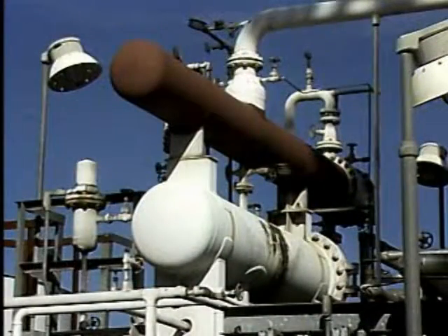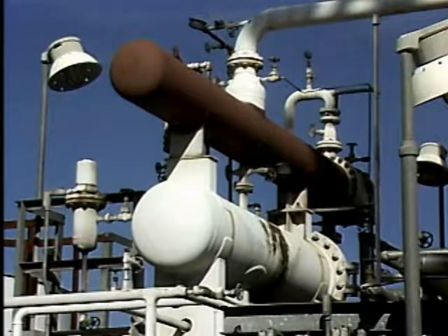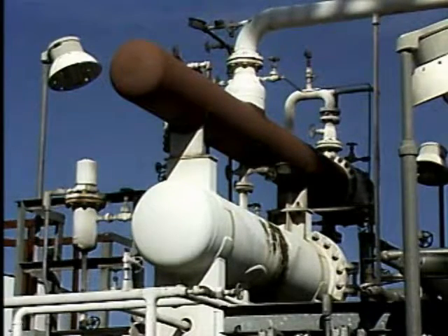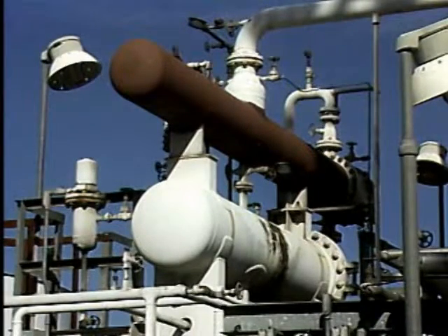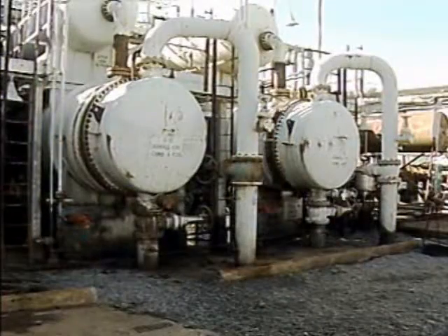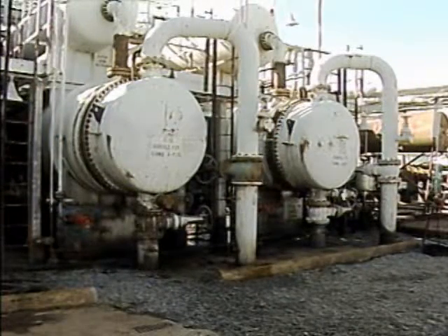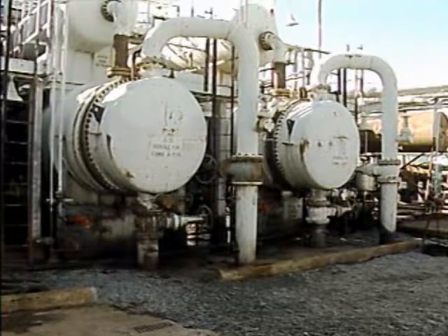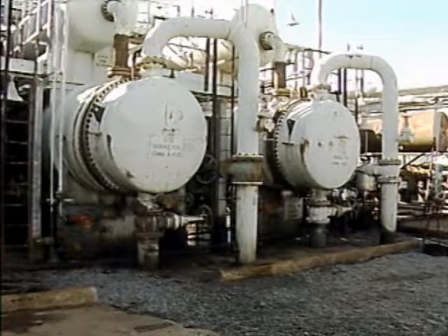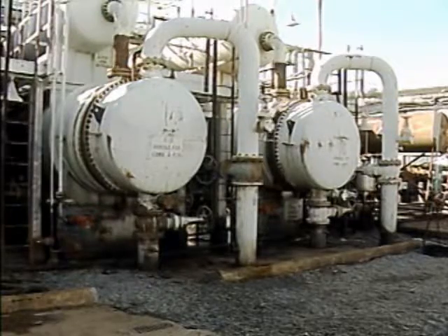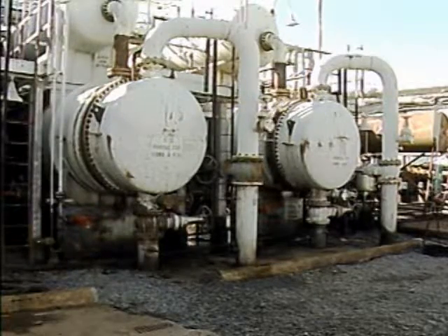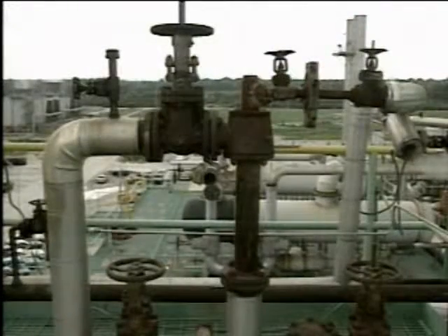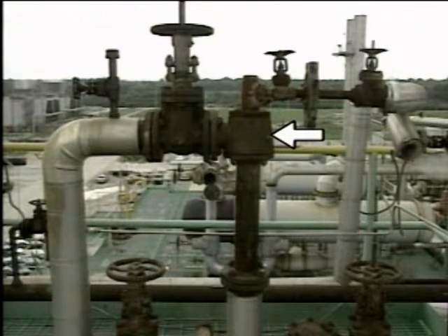For example, the vapor entering this condenser is at 250 psi, and the condenser is operating at a pressure slightly less than that. On the other hand, this condenser is operating under a vacuum, because the vapor entering it is near atmospheric pressure. In a condenser that operates under a vacuum, the condensing vapor normally maintains the vacuum. However, when the condenser is started up, auxiliary equipment, such as a steam jet air ejector, may be needed to